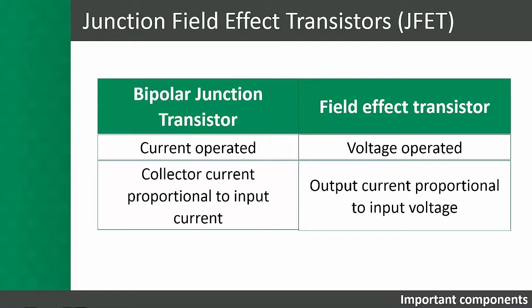Field effect transistors can be made much smaller than an equivalent BJT transistor, and along with their low power and current consumption and power dissipation, makes them ideal for use in integrated circuits such as the CMOS range of digital logic chips.